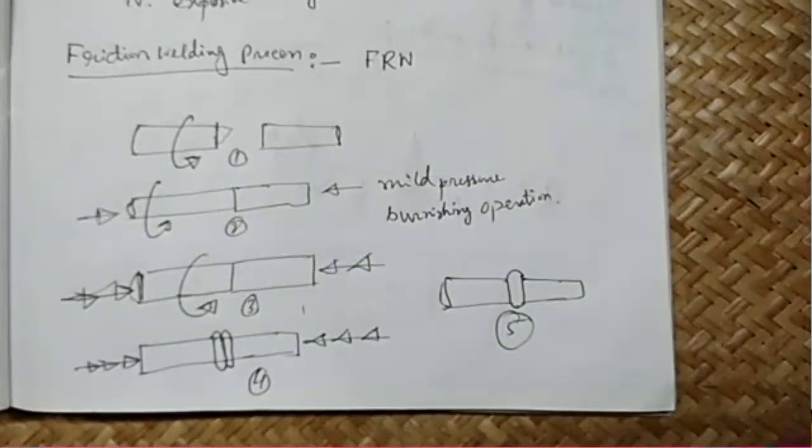The heat affected zones are usually narrow because we do not melt the material, we are just making the object a little softer. So that's why the heat affected zones are usually narrow, and since the time period is very short for heating and cooling, the radial and orbital friction welding that we will see in our video.